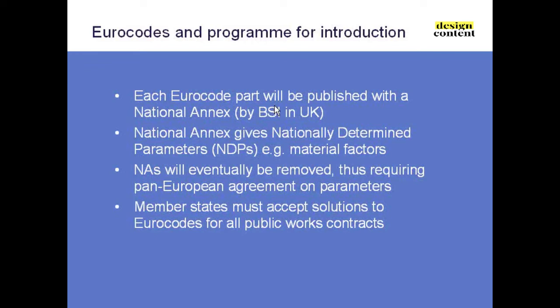The other thing that goes in under NDPs tends to be things which are very country specific, like climate. So your wind map, for example, or your isotherms will go in your national annex. There will be decisions on traffic as well, traffic loading, because that's country specific.